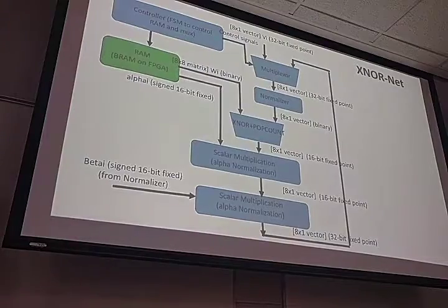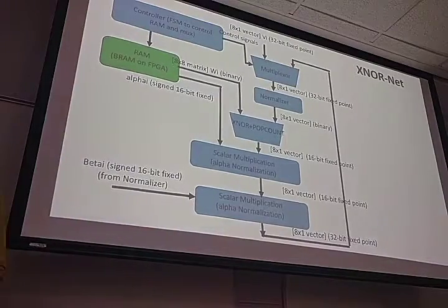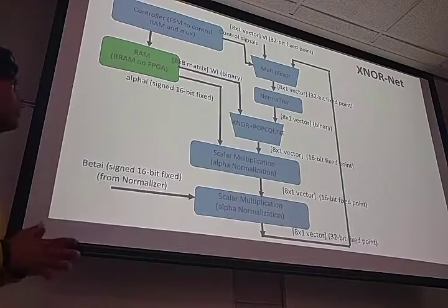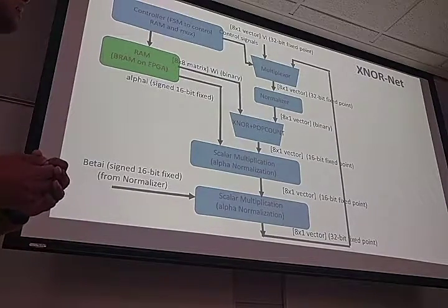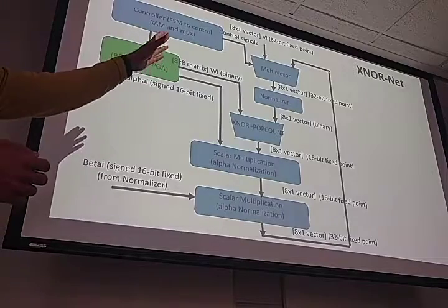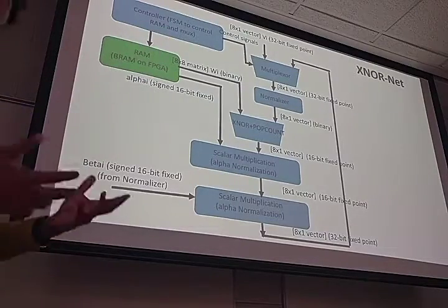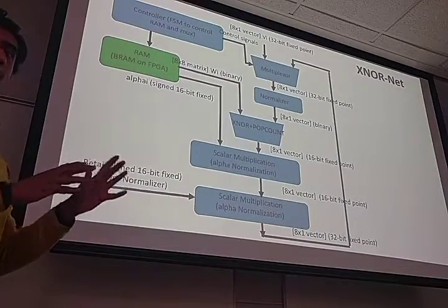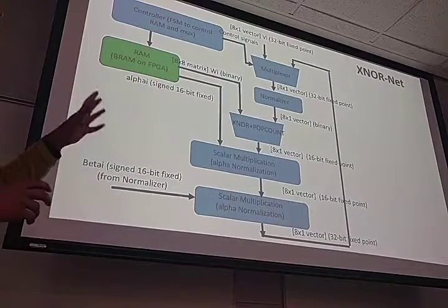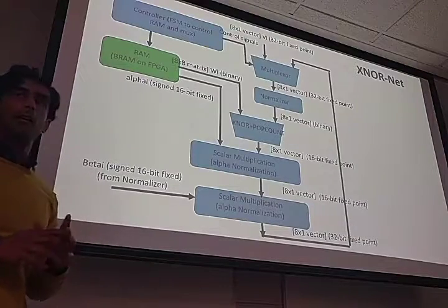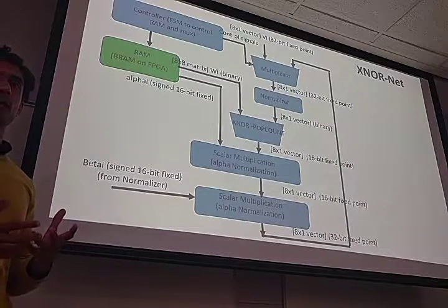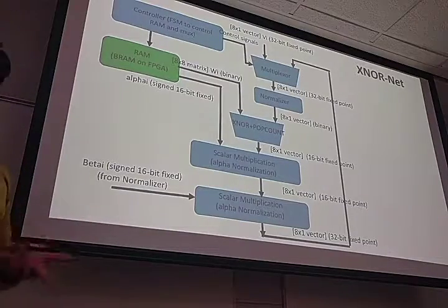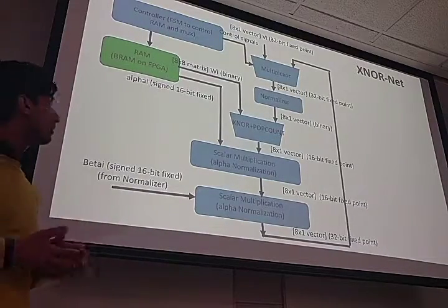In terms of the concrete implementation in hardware, the fully connected layers look as follows. The vector comes from the RAM, in our case, because the test bench we have made is in the FPGA's RAM, so it comes from the outside. It then gets normalized and converted into a binary representation, and from that we get an alpha value, which in our test bench we already have.